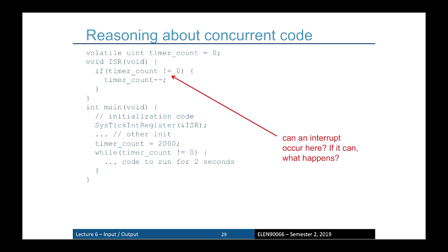In particular, if this ISR code was quite long, with lots of instructions in here, then multiple timing events can happen, and if you allow nested interrupts, it could call itself many times. It might start getting really, really messy.